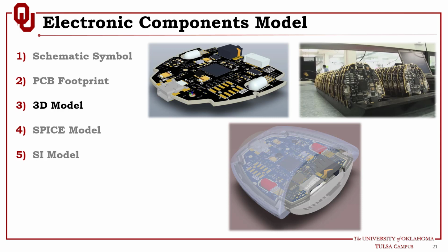Now, today's electronics products are compact and tightly packed. Look at the fitness tracker. There is a circuit board and a lot of electronics inside that, and it's highly compact. So it comes in an unusual shape and may well have a PCB that is folded to fit into the case. Now, to design a product like this, you need to be able to model the PCB in 3D so you can visualize the finished board, perform 3D clearance checking, and transfer the loaded board to the mechanical computer-aided design domain. And you have tight collaboration between the mechanical design and electrical design. And to do this, you need to have a 3D model for every single component in your board.